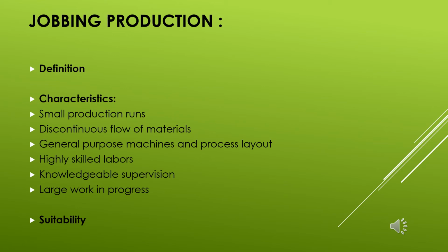As each product is non-standardized, varying in size and nature, it requires a separate job for each production. The machines and equipment are adjusted in this production in such a manner as to suit the requirement of that particular job. Job production basically involves an intermittent process, as the work is carried out as and when the order is received. It consists of bringing together the raw materials, the parts and the components in order to assemble and commission a single piece of equipment or the required product.